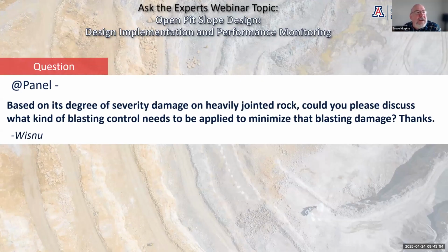Yeah, maybe just a quick, I totally agree with Dan. I think there's a lot of blocky, weak ground where people are using splits that I don't think it's worthwhile. I think my terminology is a bit different to Daniel, and sorry for that. I call it buffer blasting, but anyway, it's probably trim blasting, where you use that double stitching on the back with that half spacing and those tight spacing of holes. I think that realizes really good stuff.